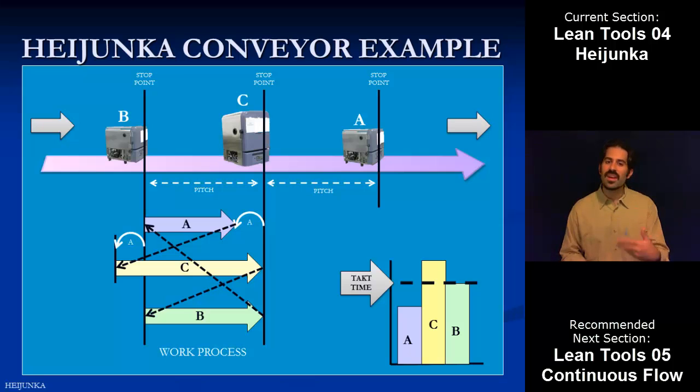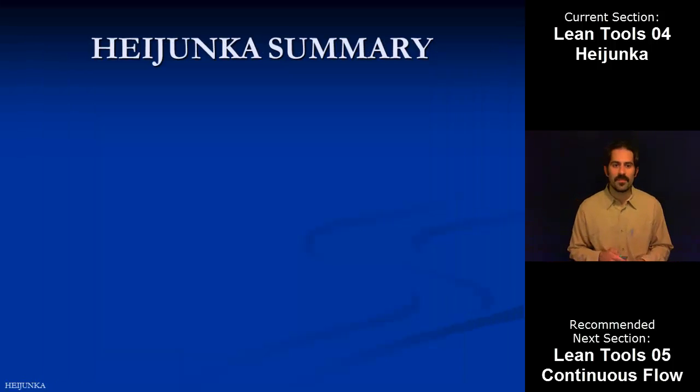So even on a conveyor system, right, this idea of balancing. If some things take less time than other things, we balance them so that on the weighted average, everything comes out to takt time, and we don't have to compensate by building up huge inventory stockpiles or having a bunch of extra people on hand just in case we need them, right? That's what we're trying to get at.